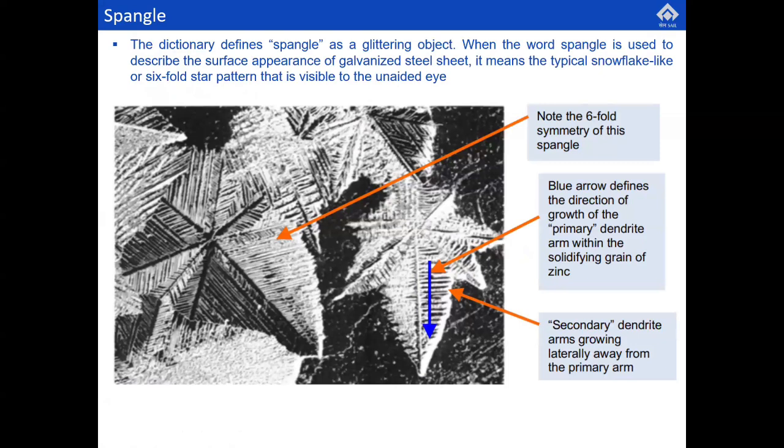Historically speaking, we have been supplying spangled GP from our old galvanizing line, but from 2018 onwards in CRM3 HDGL, our product is a zero spangle. So what is a spangle? Spangle is basically the way the zinc cools down after it passes from the zinc pot. It cools down, and these patterns are formed where there are grain boundaries. So this reflects light in a way which gives an illusion of a reflecting surface.